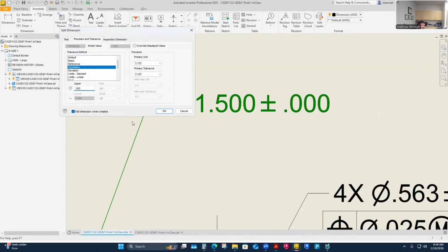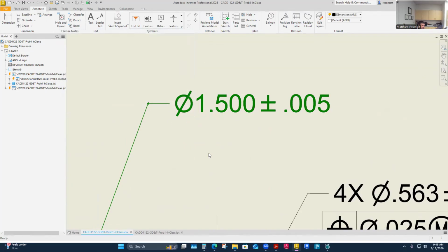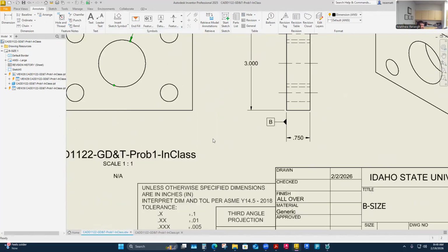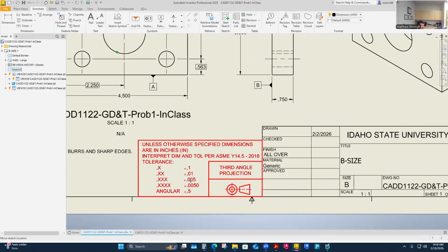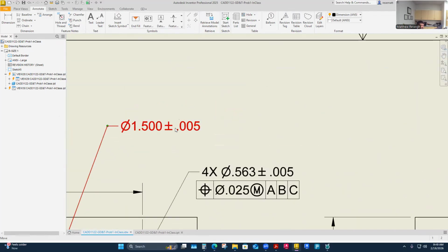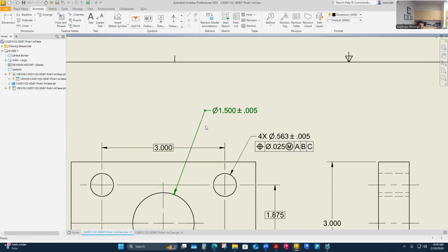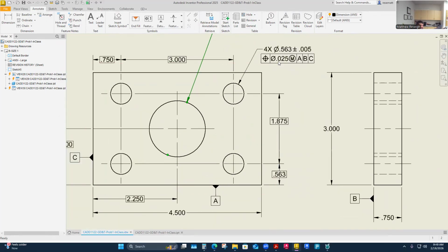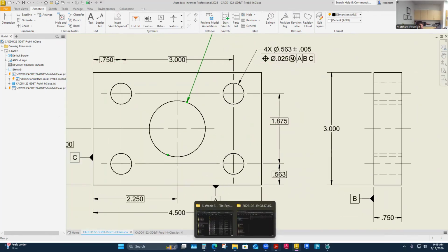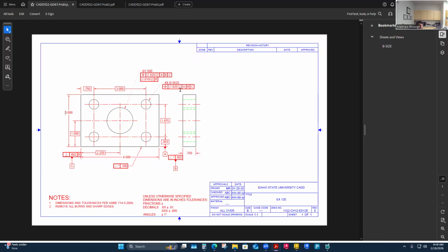That is my allowed tolerance, plus or minus 5 thousandths. It's right here, plus or minus 5 thousandths for 3 decimal places. So it gets the same. And I'm going to add the GD&T symbol for position locating. I'm really going to kind of copy this. I didn't make up these particular tolerances, but it ends up being the same. So really, I'm going to control it the same way, with exactly the same tolerance zone size even.